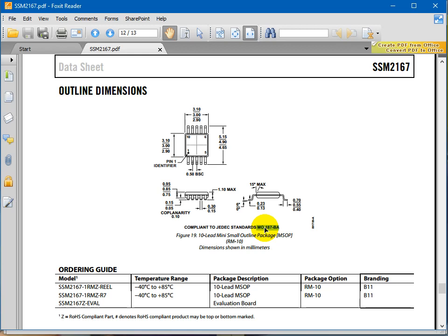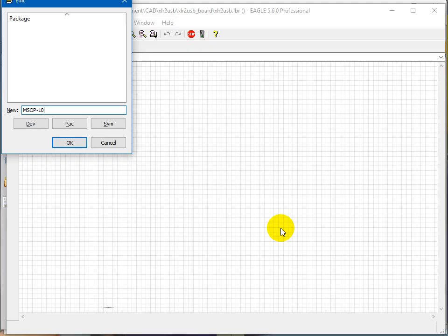You get TSOPs, but then you get exposed pad TSOPs. You get fine line BGA versus chip scale BGA versus this BGA versus that BGA. But the JEDEC standards are universal. They're registered part numbers, and they'll usually have a variant on the end. In this case, MO-187, the variant is BA. So let's begin to build our component.